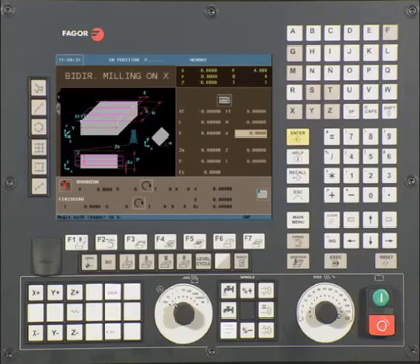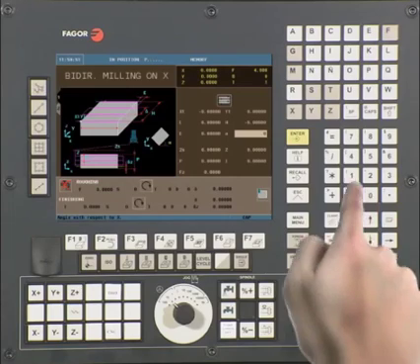A is the rotation angle of the program part about the defined part 0. The value in this field must be entered in as decimal degrees if an inclination angle is to be applied. In our example, we'll be using a value of 0. Type 0, press Enter to continue.